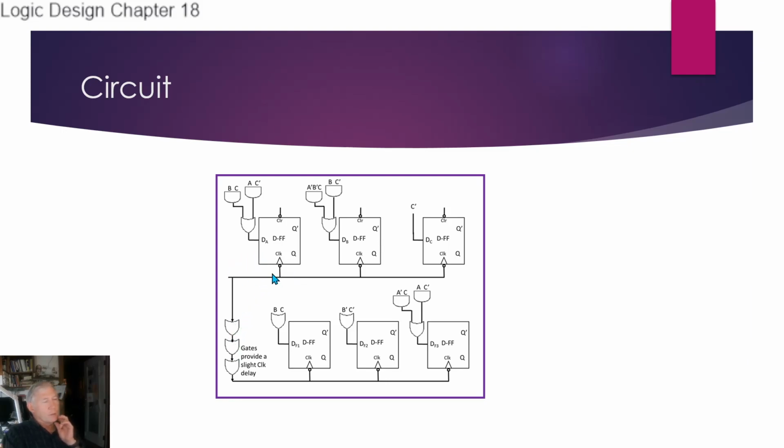But when the clock changes, there's a small time that has to expire, called the propagation delay, before the new present state is displayed in the flip-flop outputs. So we have the correct inputs here to get to the correct next state. If we're in S0, where they're all 0, the next desired state would be 0, 0, 1, for instance. Then if we're in 1, the next would be 0, 1, 0, or 2, and so forth. And when we're at 1, 0, 1, or S5, the next desired state would be 0, 0, 0, or S0.